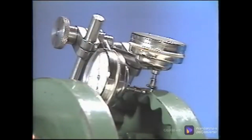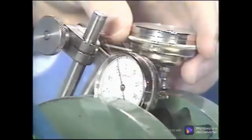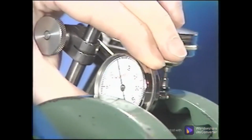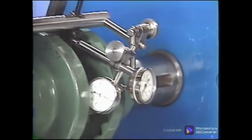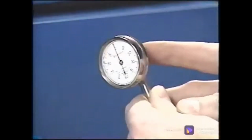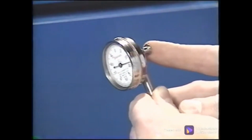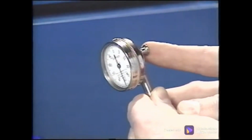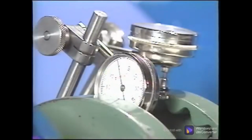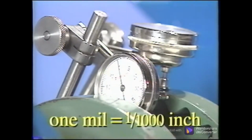The dial indicator is positioned near a part of the machine so that the pin is pushed about halfway in. The face of the dial rotates, so this position can be marked as 0. As the shaft is turned, the tip riding on it changes the dial reading with any change in the relative position of the shaft. When the plunger is pushed further in, the needle moves in the positive direction. When the plunger moves farther out from the dial, the needle moves in a negative direction. Most dial indicators are designed to measure in mils. 1 mil equals 1/1000th of an inch.